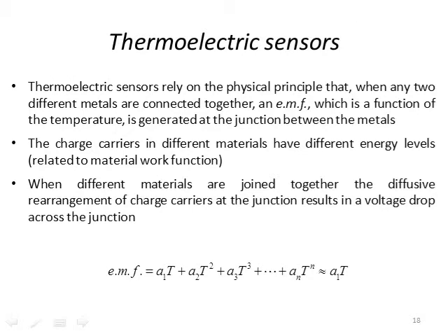Now, thermoelectric sensors, these are the first sensors that we'll talk about. These are contact type of sensors. The thermoelectric sensors are based on using two different types of materials. When these two materials are put together, connected together, they create this EMF, this electromotive force between the two of them. And when they're touched together, we get this EMF, which is then also a function of temperature.